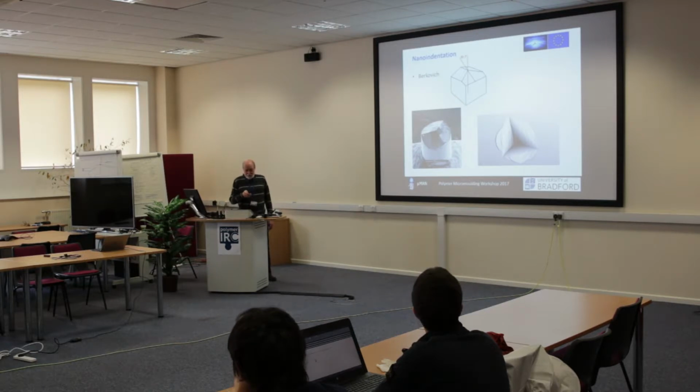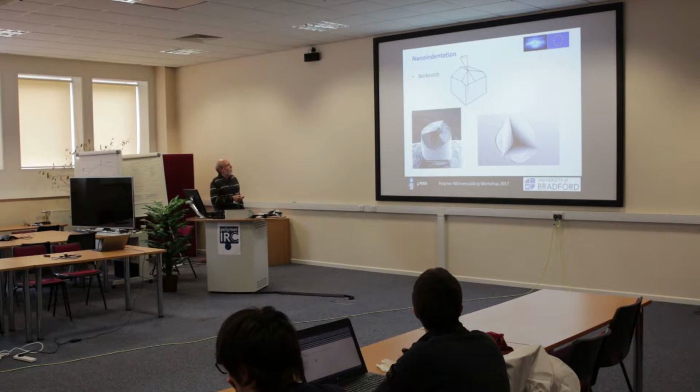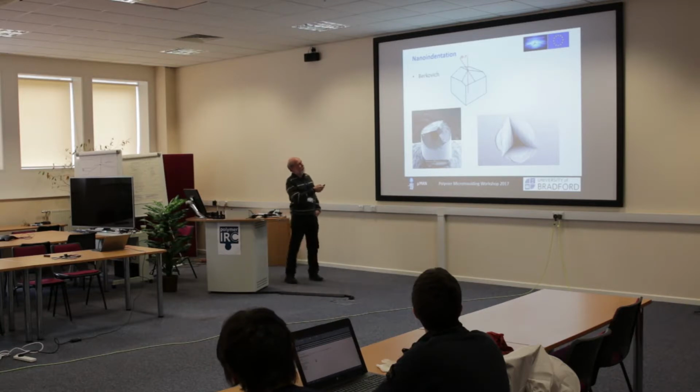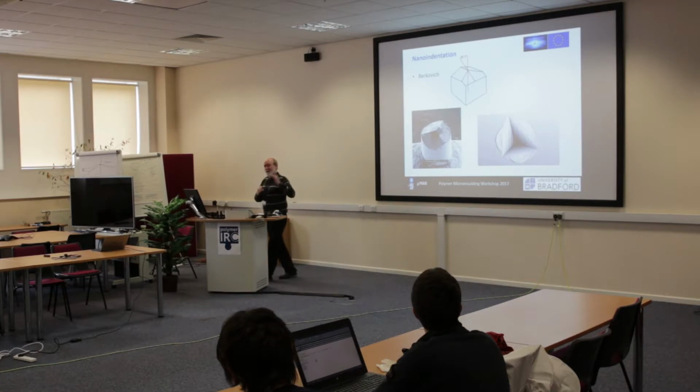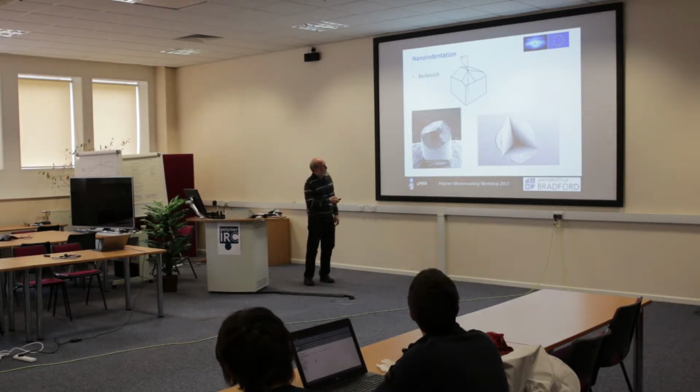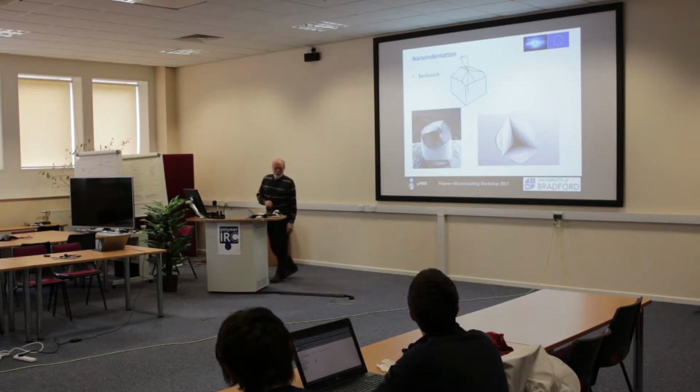So the typical, this is relative to what you've seen, I'm sure. You end up usually using this kind of Berkovich indenter because it's a way of making a sharp point. The geometry is like this, I guess, because the easiest way of getting a sharp point is if you can make 3 planes intersect at a point. So that's why it's that particular shape with a standard angle. It looks like this, and you make an indentation. Once you've taken your indenter out, you've got something like that.